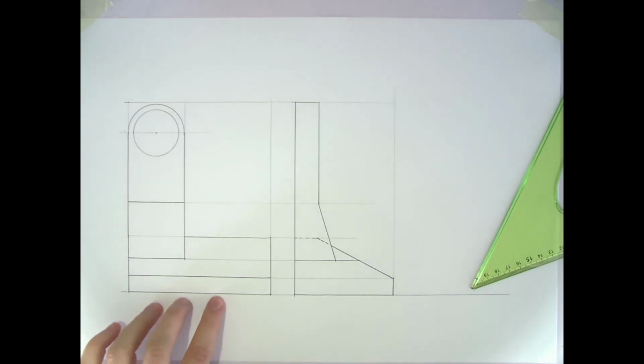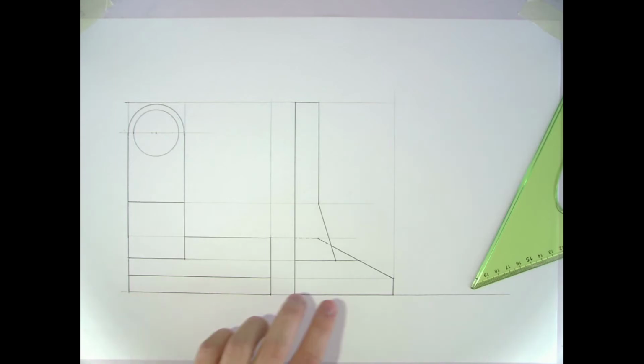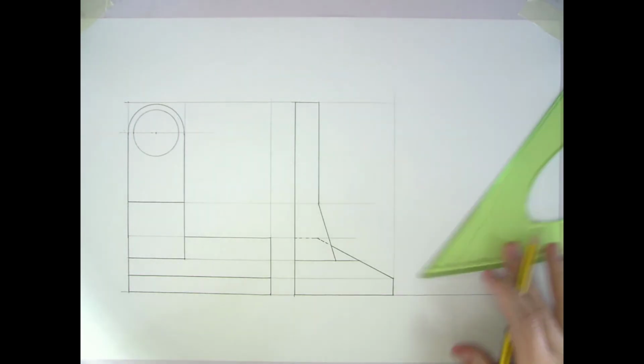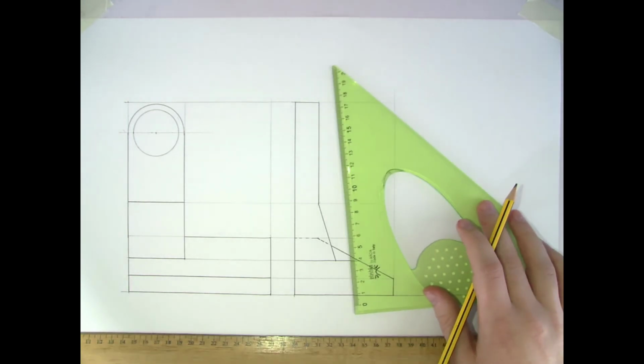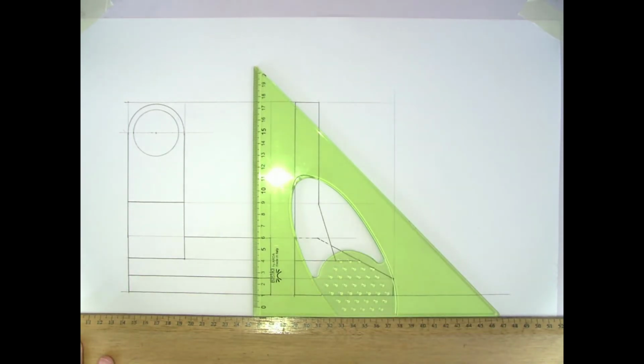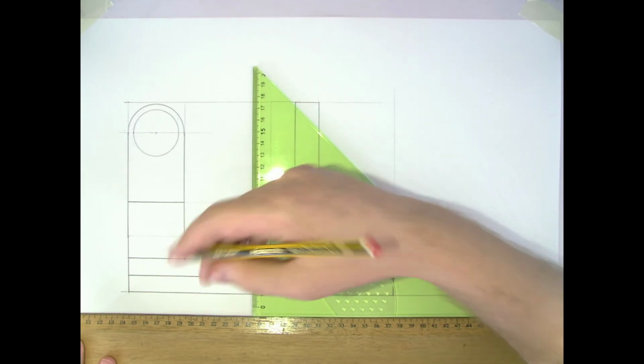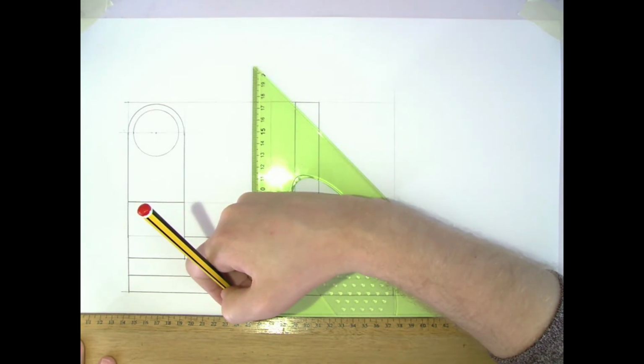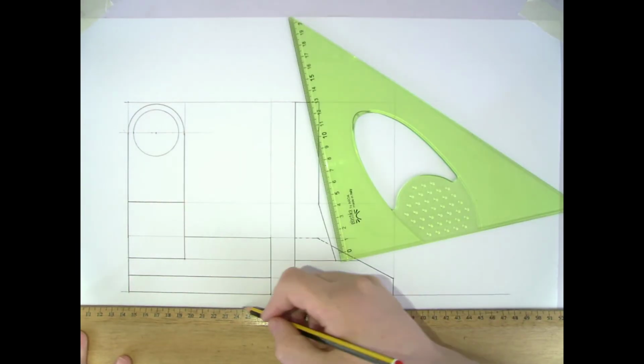So this is the elevation, part A of the question, the end view, part B of the question. The only thing that needs to be done now is to insert any 4 dimensions. So we're given all these dimensions in the question, so we just need to copy any 4 of them. Let's do these neatly. So what I like to do is measure down just 10 millimeters underneath the line that I'm going to mark, and I'll draw a light line across there.